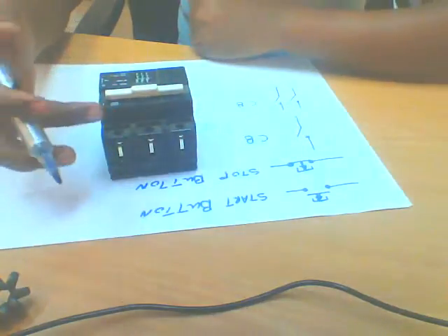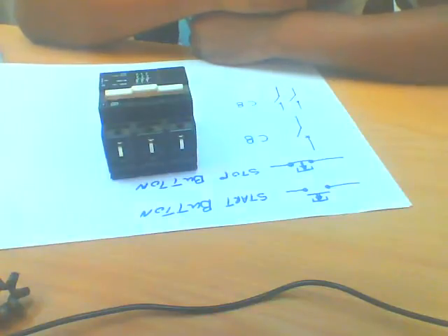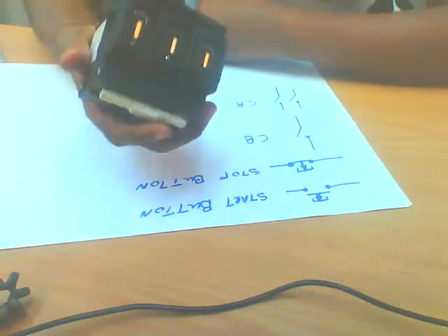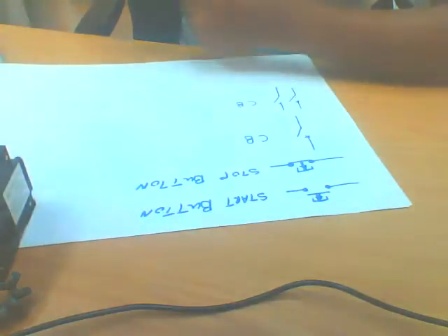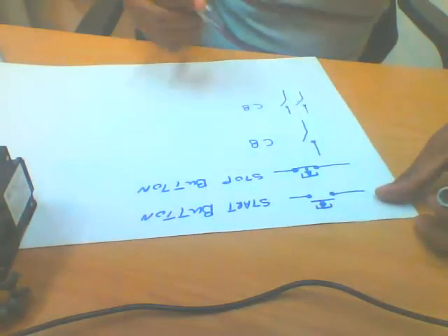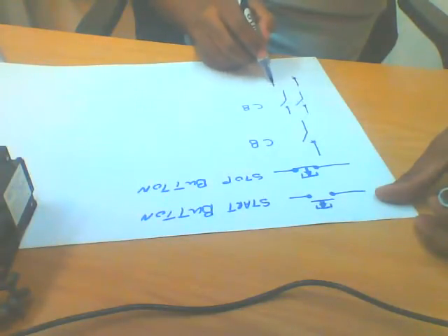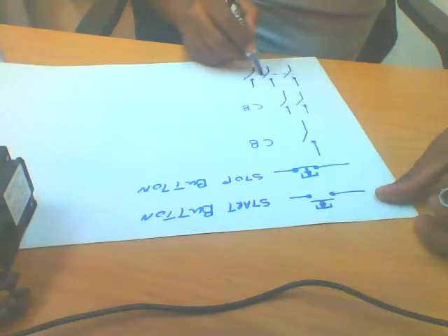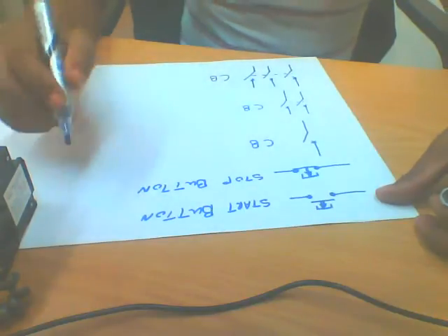You can actually see it's got 1, 2, 3 poles. This one can be used to control 3-phase power. We'll deal with that again as we move on. For a triple pole circuit breaker, the symbol will look like this. That also is mechanically coupled. That also is a circuit breaker. All right, happy?